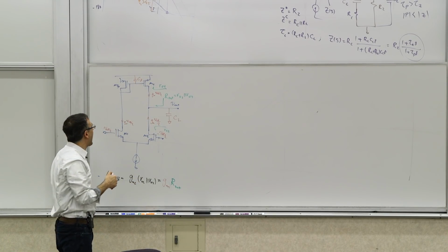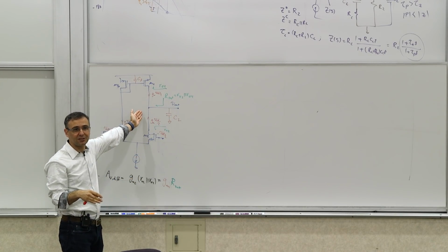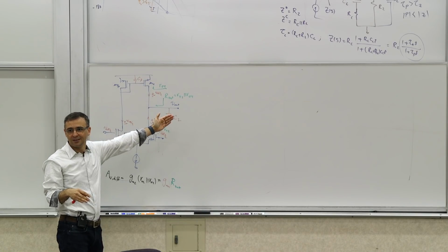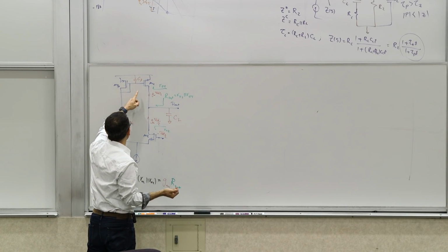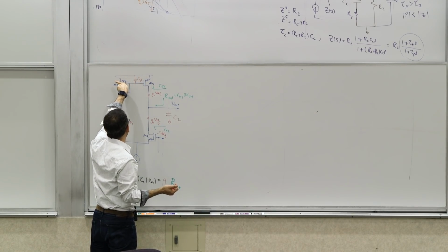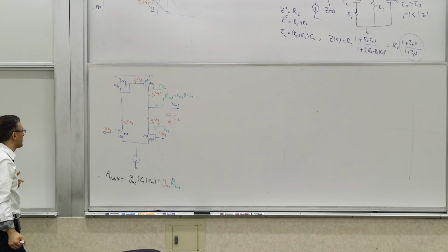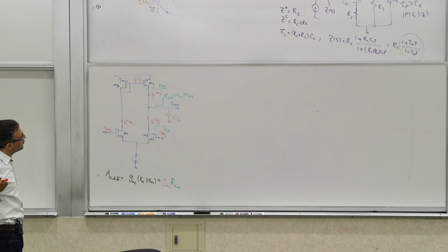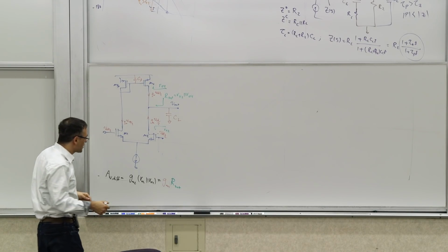If you have only two time constants, you know that the other one has to be uncoupled. But in this case, it's easy to see. If you short circuit or open circuit this one, the resistance seen by the other one is still 1/gm3, or RM3. So there are two uncoupled time constants, and there's a zero in this system. So let's talk about it.